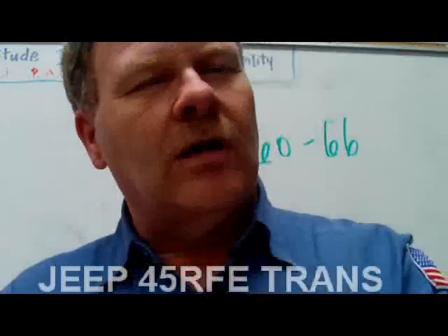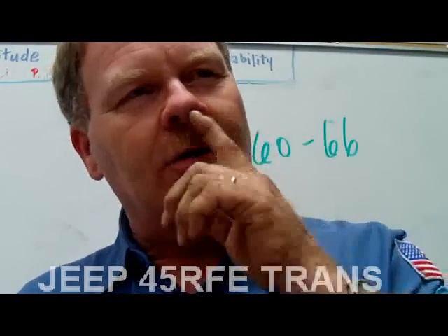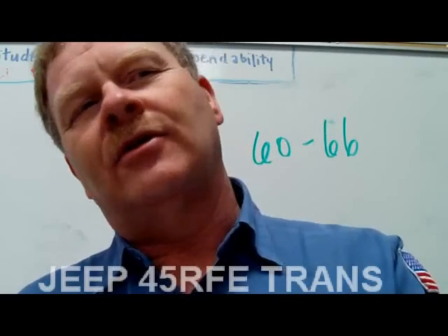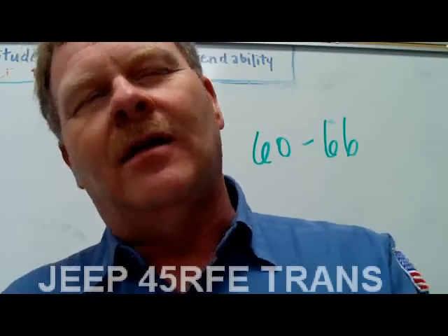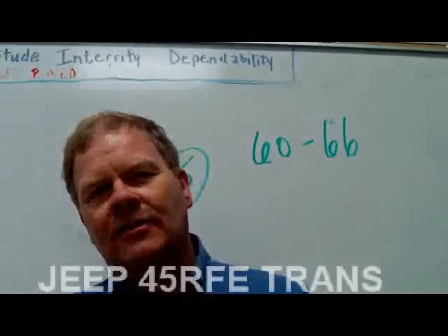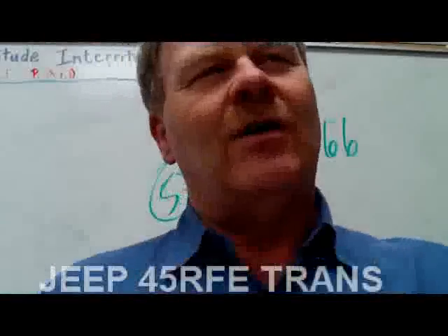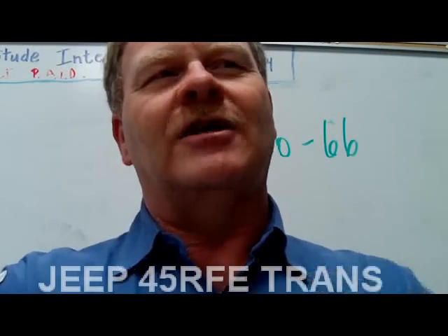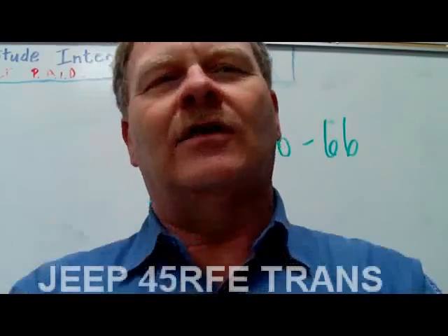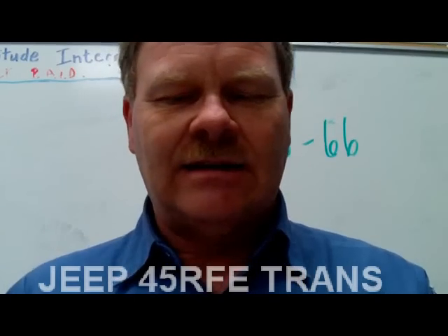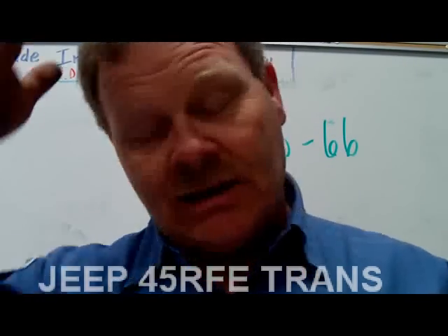The front end work, like you and Tyler are doing over there, is taking you all a while, but you're learning a heck of a lot about the alignment angles when you're trying to set caster and camber. You see how, when you set one and get it perfect and then make another adjustment, it throws this one off. Yeah. So you have to learn how to do that the right way. See, and it's a good thing that you guys are sticking with that.